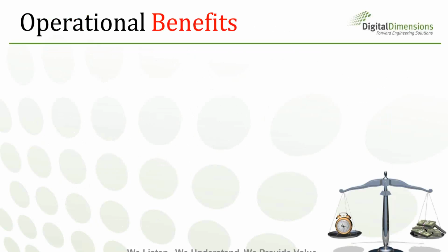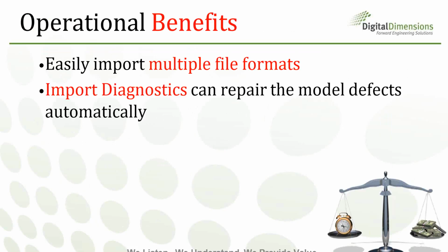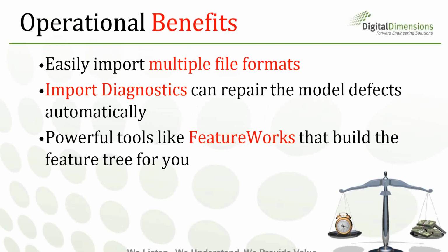Some of the benefits of utilizing SOLIDWORKS for these types of operations: you can easily import multiple file formats. We talked about a ton of those. We have the import diagnostics, which can repair your model defects automatically. And then we have powerful tools like FeatureWorks that will build that feature tree for you. Just be aware, like I said, about the undefined sketches, making sure that you correct those things and checking your tree. It doesn't always know the design intent for that part either.